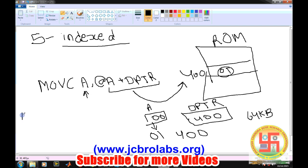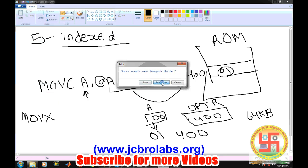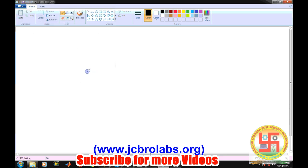Similarly, there is another instruction to access the external memory. The previous one is used for the code memory or the on-chip memory. But suppose you have connected external memory, then the MOVX command is there, and that MOVX command is used to access the external ROM location address. So these were all the addressing modes which are supported by the 8051 microcontroller.